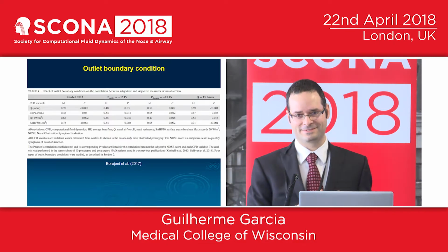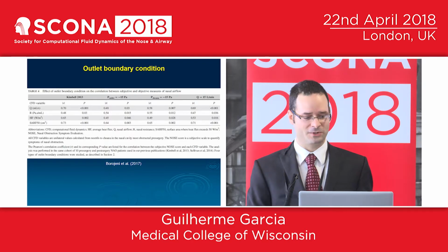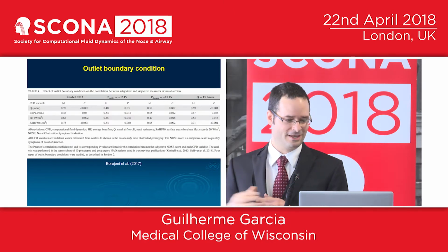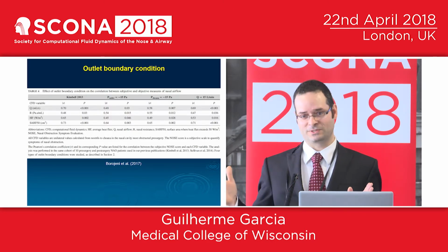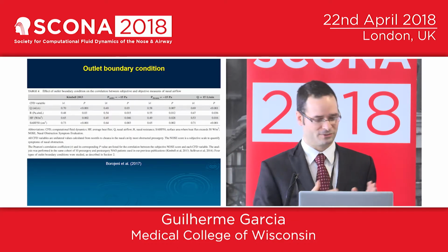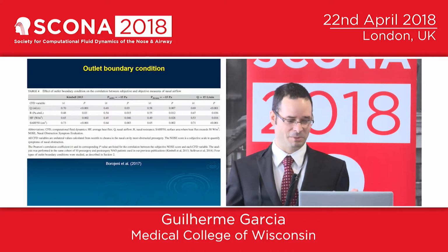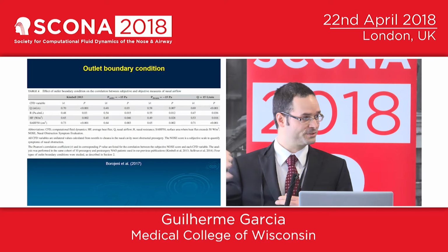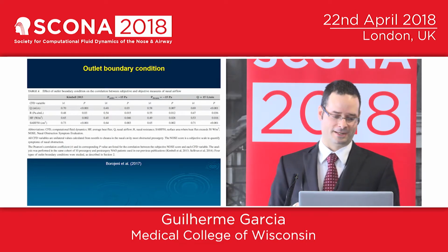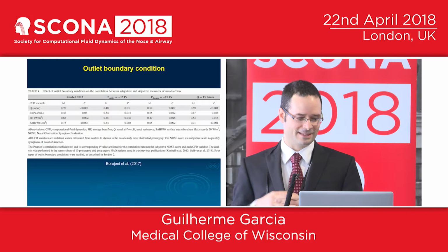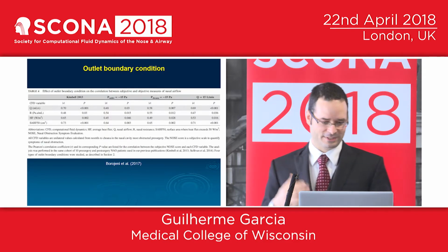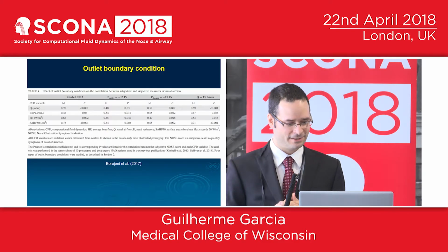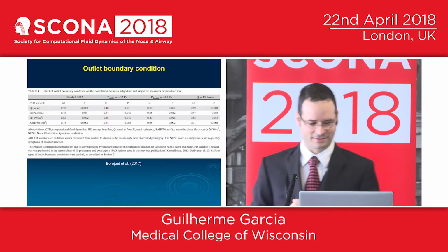And since the overall resistance of the model is the nasal cavity resistance plus the nasopharynx resistance, if we're setting this constant pressure drop from the nostrils to the outlet in all the patients, or even the same patient before and after surgery, and then you have different configurations of the soft palate, then that leads to a confounding factor, right? So we did this analysis comparing different outlet boundary conditions in, I think it was a group of 15 patients, if I'm not mistaken.